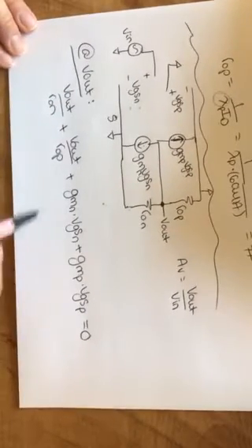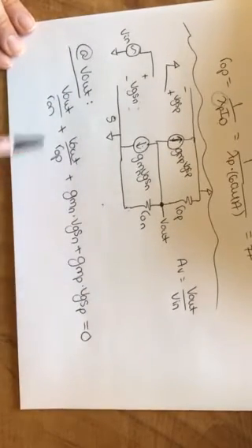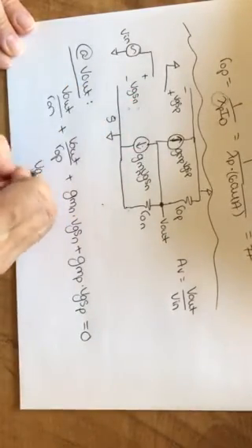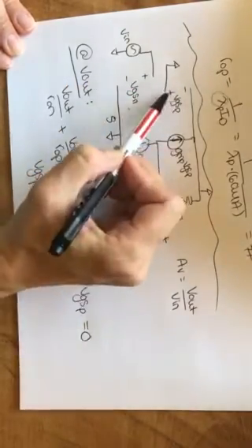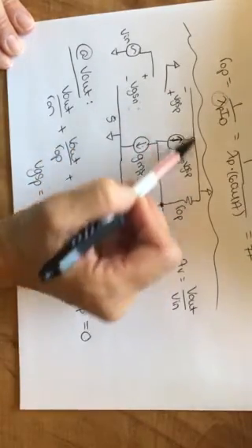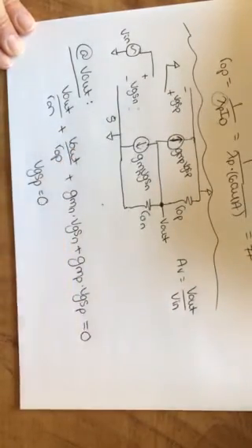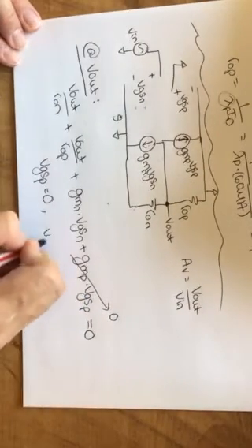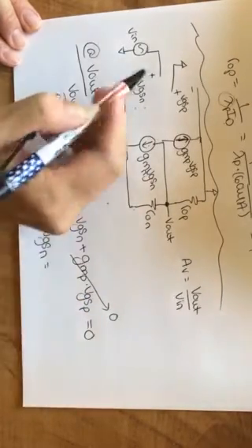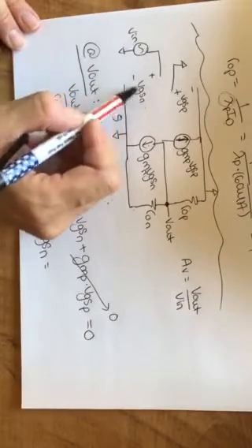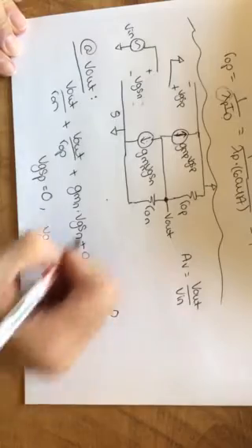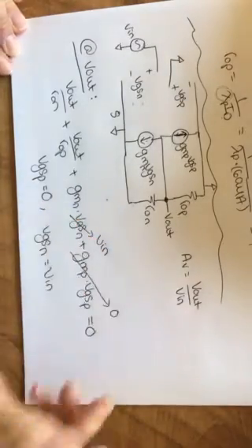I've got one equation with Vout and VGSs. I can write an equation for VGSP, which is actually 0, since you've got a ground at your gate and a ground at your source. So this whole term will go to 0. And VGSN is actually just Vn, right? The source is ground and the input is at the gate. So I can replace this VGSN with Vn.